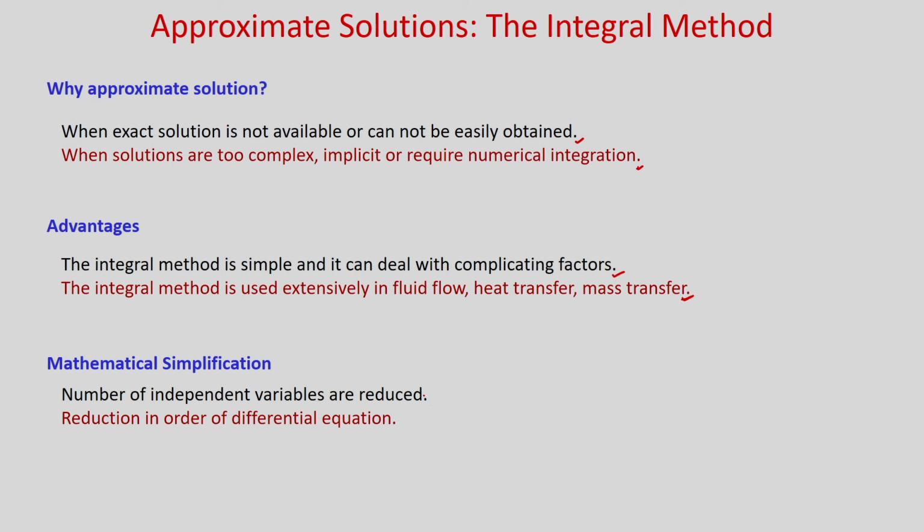The mathematical simplifications are there in approximate solutions because the number of independent variables is reduced. When you consider a two dimensional situation, you can see that using the integral method you can convert the partial differential equation to an ordinary differential equation. So, you can see that there is a reduction in the order of the differential equation.